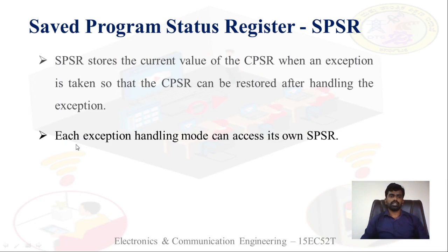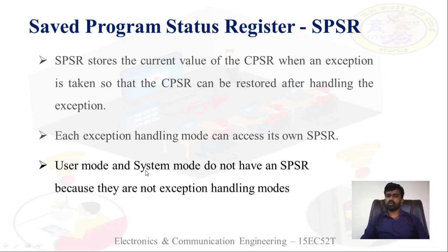Understand? Each exception handling mode can access its own SPSR. Except user mode, we have 6 modes, of which 5 different SPSRs are present. User mode and system mode do not have a saved program status register because they are not exception handling modes.